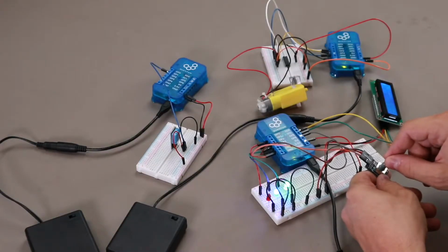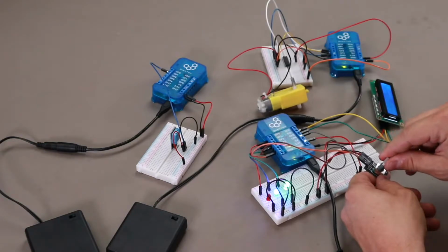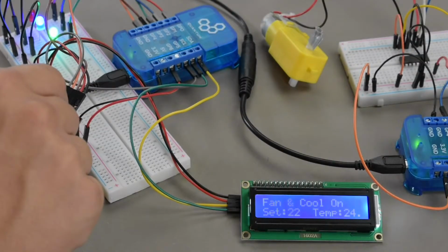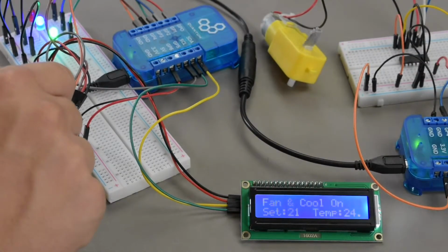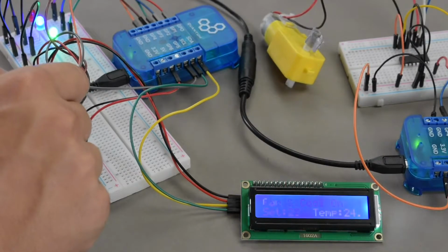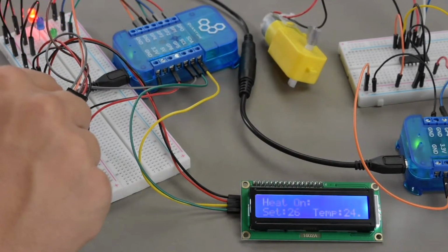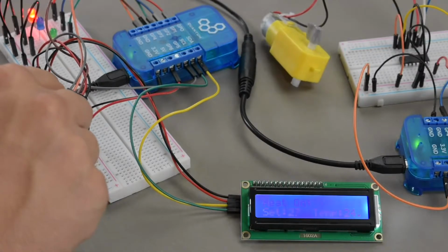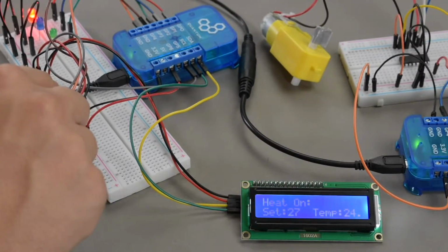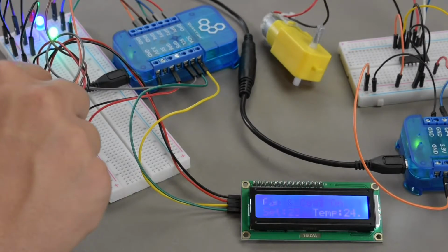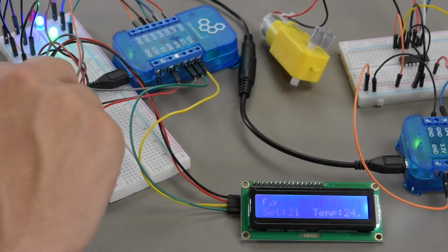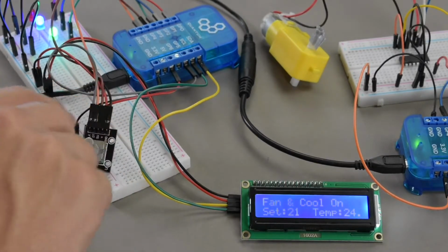The HVAC system is simple. It is used to set the desired temperature. The temperature sensor is sending its measurement to the system. The app then decides if it has to start cooling with the fan enabled or heating with the fan disabled. Based on what the control unit is doing, the LEDs are representing the state. For example, when the system is cooling, the blue LED will be turned on and the green LED will indicate that the fan is operating as well, while the red LED remains off.